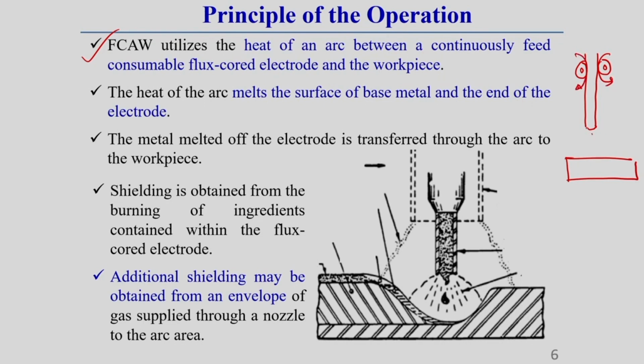it continuously rolls this consumable wire. So, here the arc is generated between this workpiece and this electrode, which is consumable. What I am telling, understand? That means this electrode burns and a droplet forms, and this droplet transfers from the electrode to the workpiece.